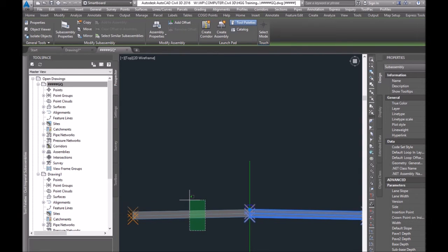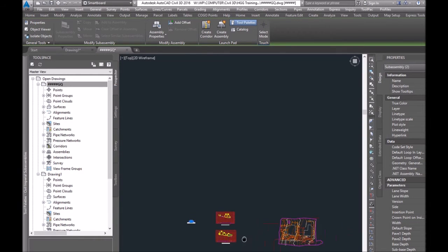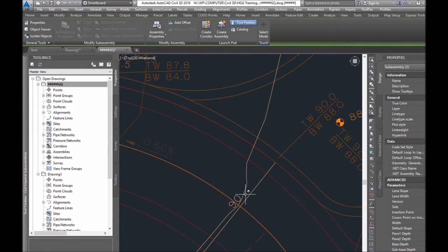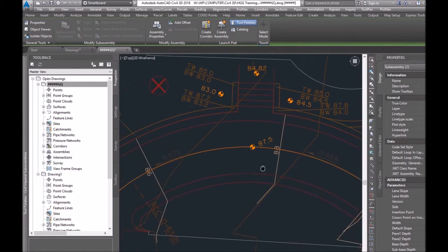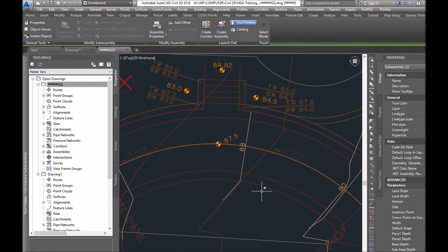So they're not even being incorporated right now. These are strictly internal. So I'm going to set these to grade one way. This driveway, I want it to slope. If I'm looking at these polylines that we drew in, and once again, this is as if you got this set of plans from someone with red lines and you're trying to implement it, it looks like it's just flat all the way across, with then some kind of grading on the side.